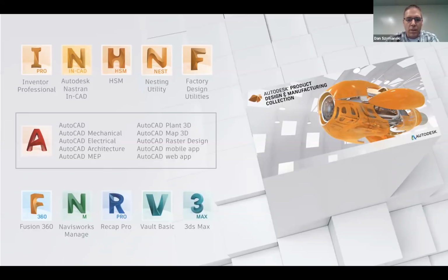There was one question I'll take. That was, have any changes or bug fixes been made to iMates? Not for the 2020 release, but we are looking at investigating some scenarios where the named iMates aren't necessarily working as expected, long-standing issues in iMates. So again, they do work as they always have with the Alt key and placing from content with the iMates or placing with iMates enabled. But we are investigating a couple workflows, specifically the named iMates, that we'll be looking at at a future time.